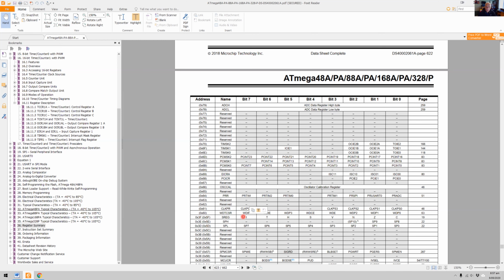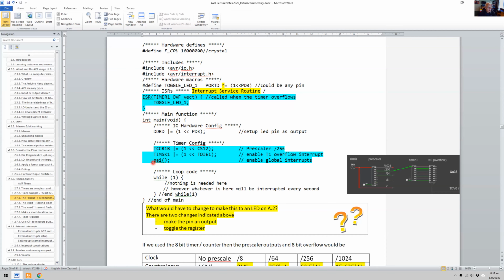set to 1. And so at any particular point in time, you can disable interrupts very briefly to do something. If it's timing critical for some other reason, or it's really important and you don't want it to get interrupted, you can turn them all off and then turn them all back on again using this. And that's such a useful feature that in C for the microcontroller, instead of actually setting the bit ourselves, there's a little function, SEI, set interrupt. The alternative function to clear them is CLI, clear the interrupt flag.